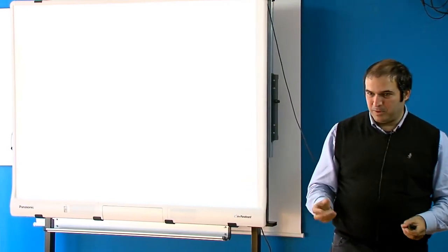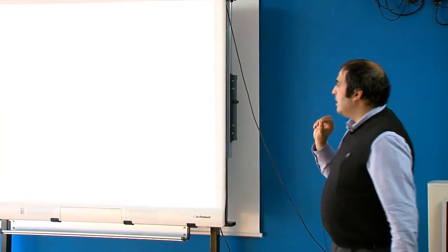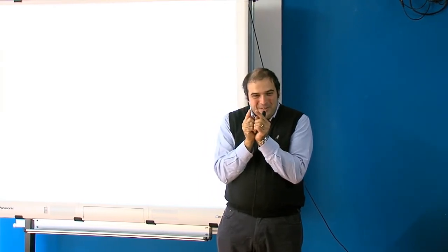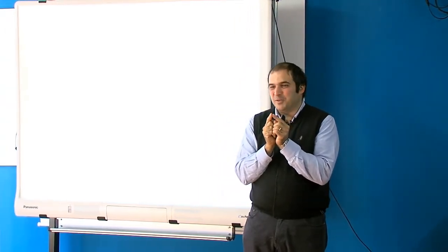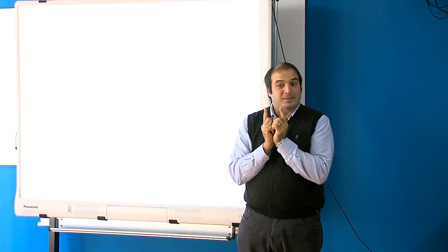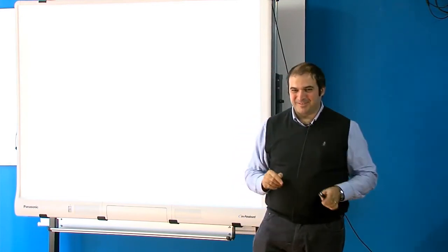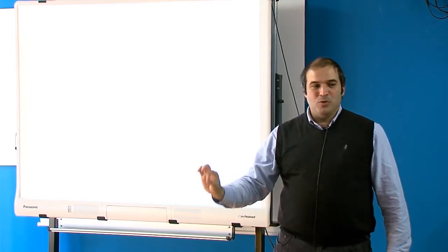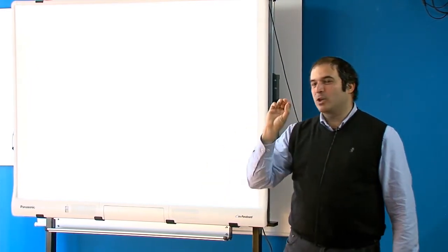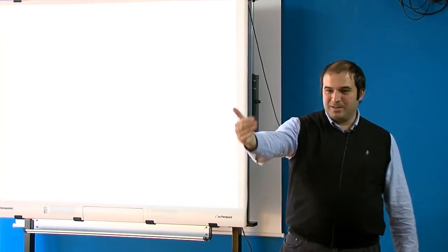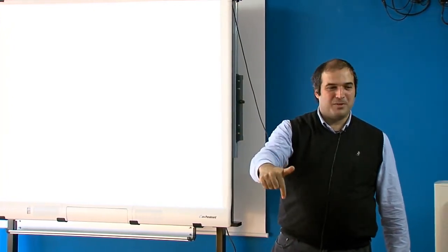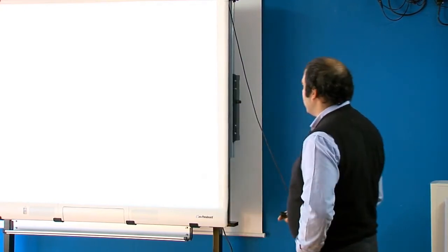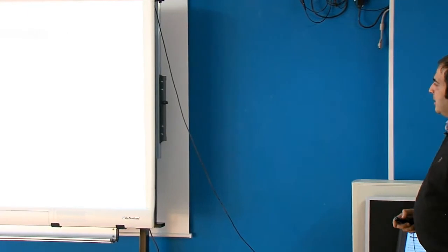This is another big problem, which means that depending on the tone spacing of the multisines, I can have a problem. And you say, okay, so what should I do? I don't know. The best thing to do, from my point of view, is to use an input signal as close as possible to the signal you are going to use if you are going to use that device in a specific case. Okay, let me follow.